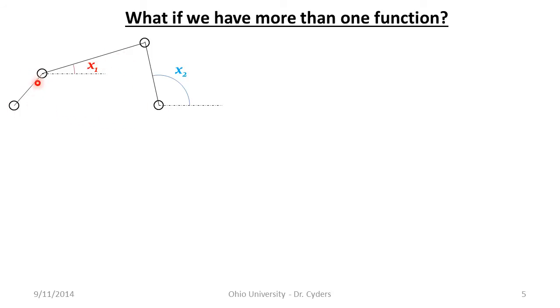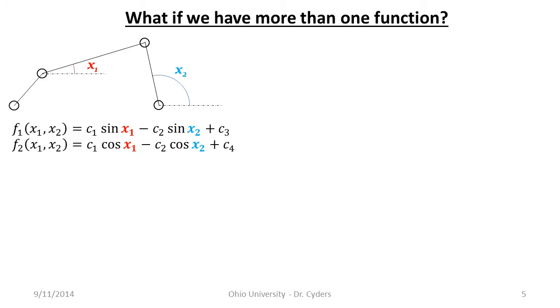And so if I know the position of these 2 points, so this point and this point, then what are angles x2 and x1? Can I solve for those? And we surely can. We can draw what are called the vector loop closure equations and come up with 2 equations, one that describes the equations in x and one that describes them in y.